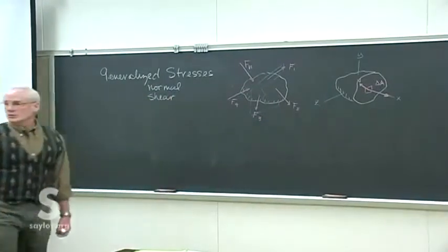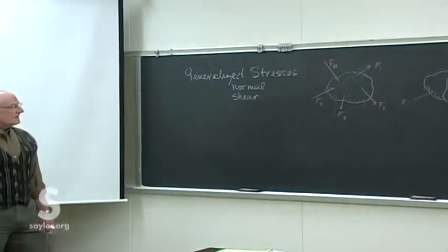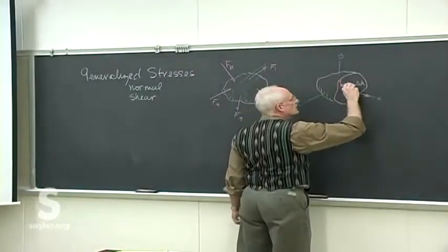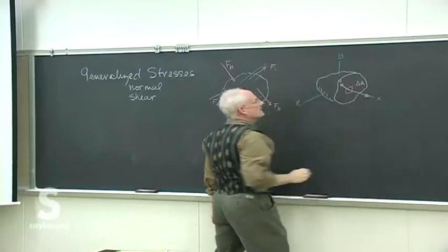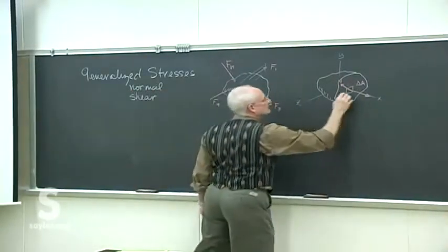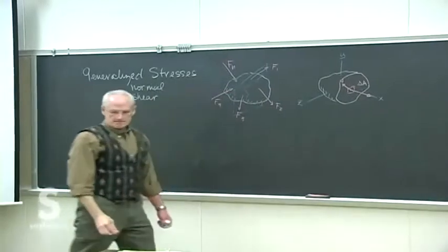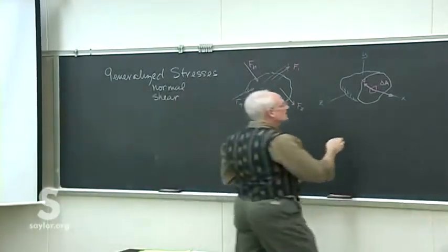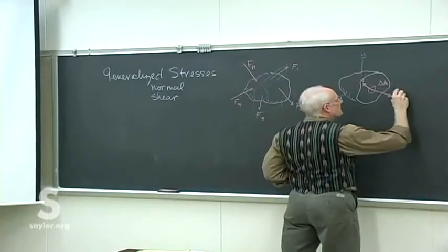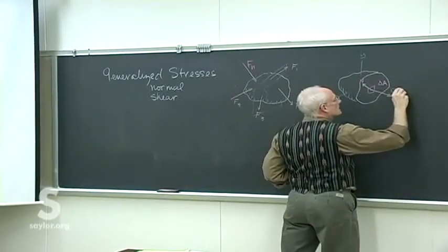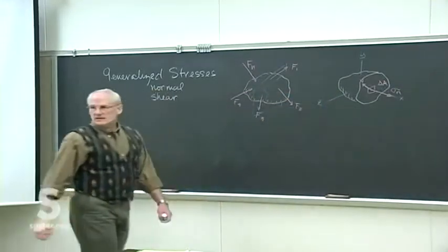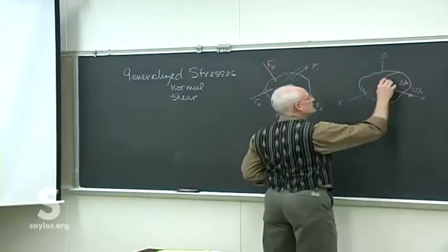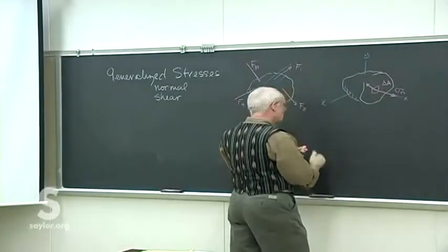So often some direction parallel to that face is some shear component, and it's the two of those together that came from the resultant force of all of these original forces acting on it. So since they're both acting on the same area, we can make the components not the force components themselves, but the stress components, because they're both divided by the same area.